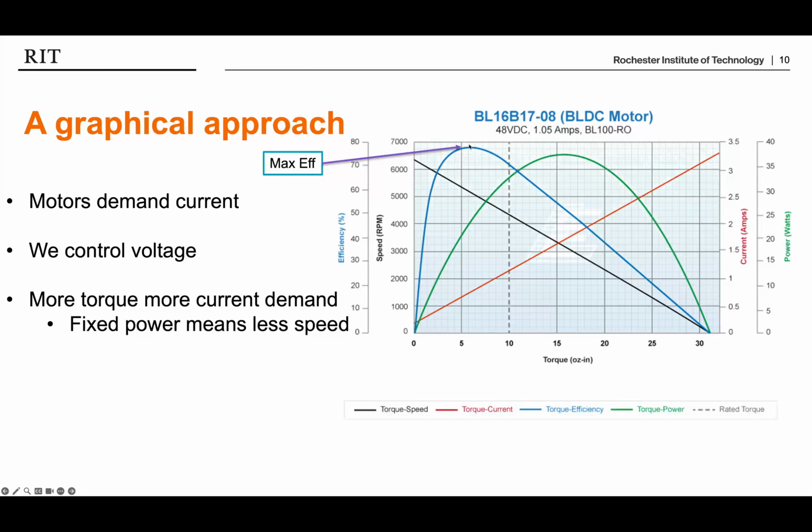In other words, on this side, we are being less efficient and we're converting more energy into heat. On this side of this curve, we have not yet used all of our capacity. We're basically leaving some of our input power on the table. We're building these electromagnetic fields and then we're not really using them to full effect.